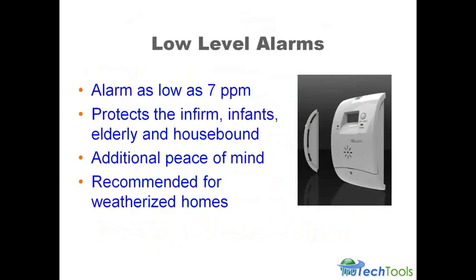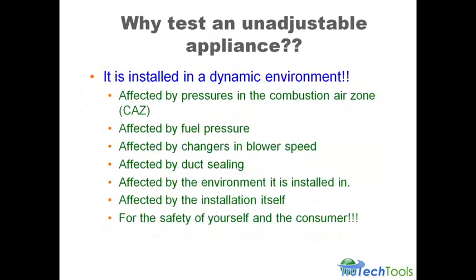So why test an unadjustable appliance, right? This is the question I got from the contractor. I said it disturbed me a little earlier. Well, because that appliance is installed in a dynamic environment, right? You put your furnace in the basement, you hook the thing up, it's affected by pressures in the combustion air zone, right?